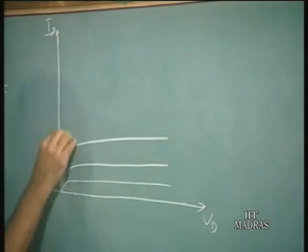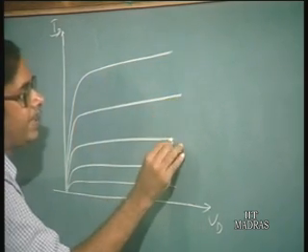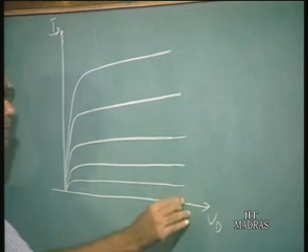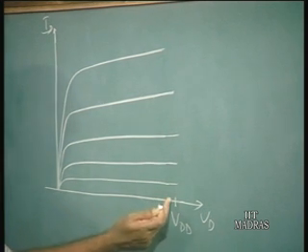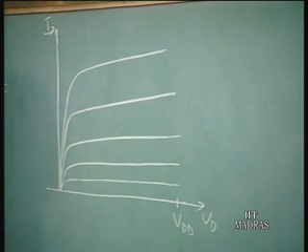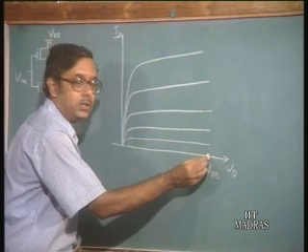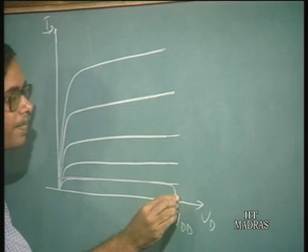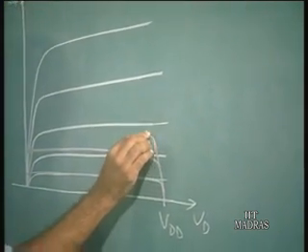This is the NMOS transistor characteristics, okay, and then the load transistor characteristics must now be drawn with VDD as the origin. So, this is the VDD point, say. So, this is the origin point, and now we have to draw the characteristics of the load transistor. Okay. Now, the characteristics of the load transistor, I will draw this way, coming this way.